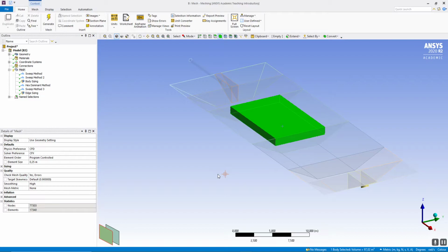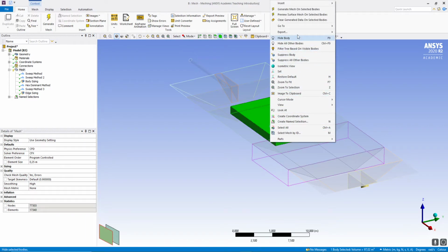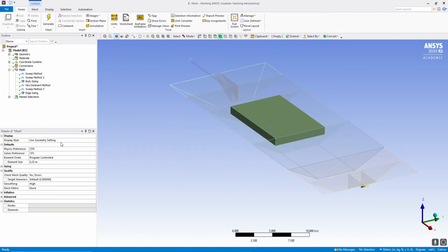All right, and furthermore, this region also has a very high velocity gradient because it's going to be a porous region when we set it up in the CFX Pre. Okay, so it will have very different velocities inside of it, especially in the regions contacting the outer channel. All right, but now let's clear this data.